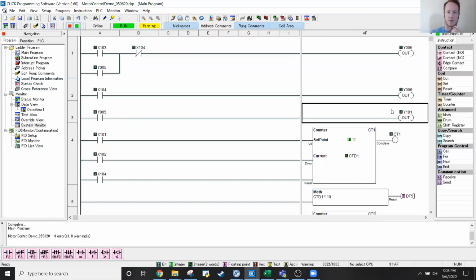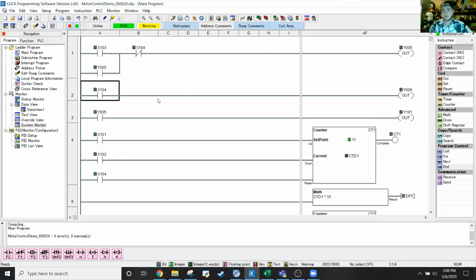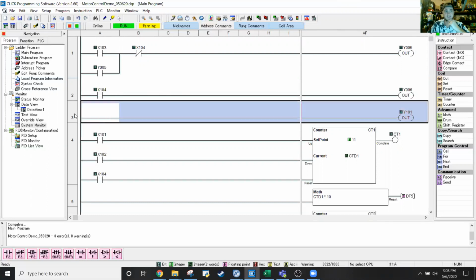So you can't just directly engage the contactor. There has to be a signal. What we could do is just delete this, so then rung 3 would always energize as the PLC is scanning, and it would always fire that output, right?